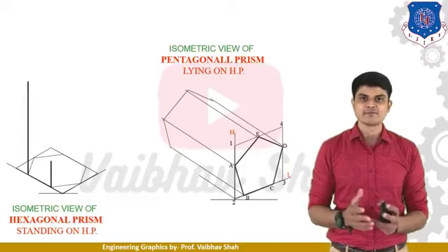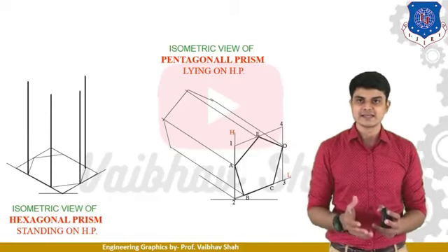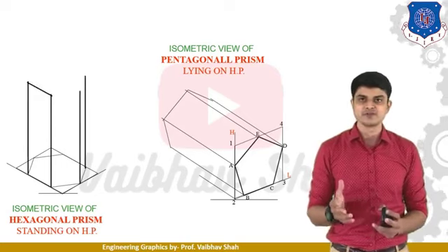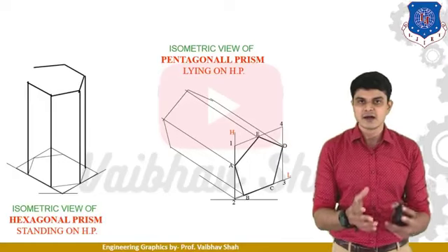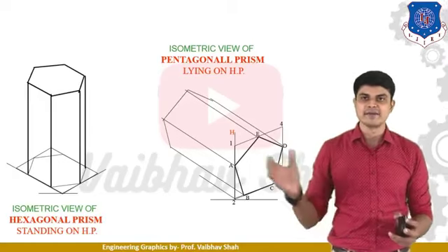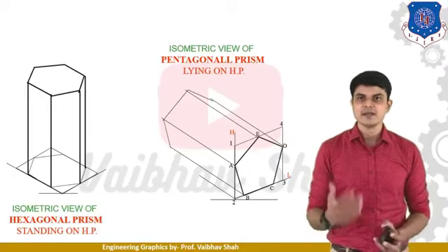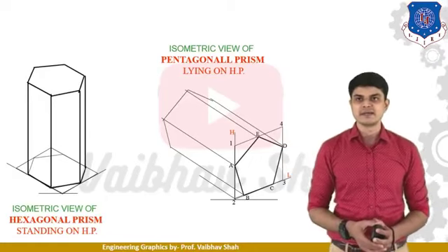So we'll be drawing 80 mm from each and every point of the hexagon like this. And then after having the end points, you need to just connect these end points by a straight line. You might be having this joint like this, and you will have this hexagonal prism generated. Very easy. Let us move to our next problem.